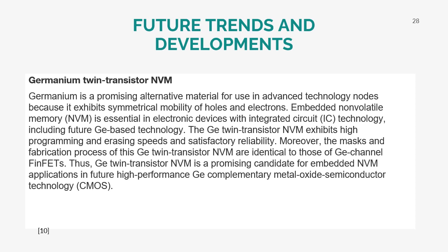The germanium tin transistor exhibits high programming and erasing speed and satisfactory reliability. Moreover, the mask and the fabrication process of these germanium tin transistor non-volatile memories are identical to those of germanium channel FinFETs. Thus, germanium tin transistor non-volatile memory is a promising candidate for embedded non-volatile applications in future high performance.